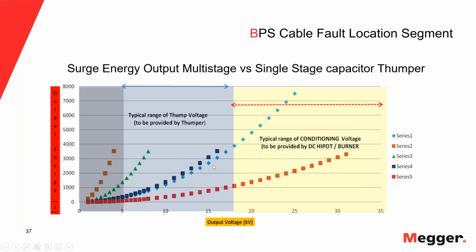And you can see if I go down in voltage to 10 kV, how many joules do I have left? Maybe 1,200 joules. That's a big cry away from the 7,500 joules that the nameplate says. So 1,200 joules is much less noise than what I would get at 7,500. But I cannot use 7,500 because it'll destroy my cable. So that's the old saying, the surgery was very successful, but the patient is dead now. We don't want to do this with network cables.